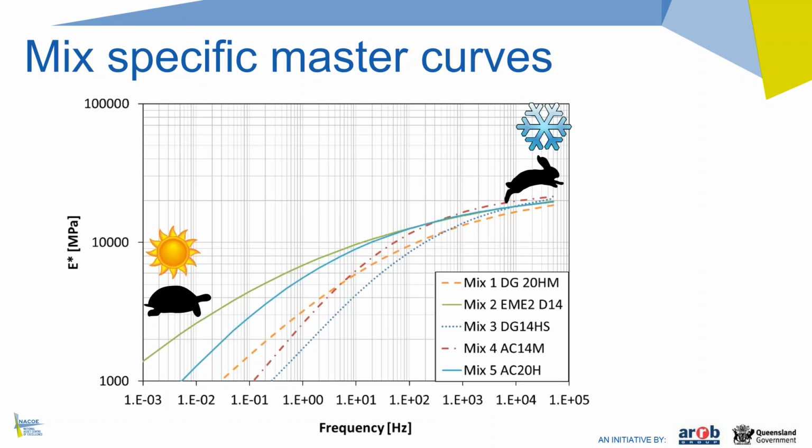No, well, the answer is actually that it does asymptote on both sides. The sigmoidal model is actually a symmetric model. That means the asymptote that's on one side is also on the other side. The thing the slide doesn't show is the current Austroads method, and also the current design, the current TMR supplement, limits the master curve at 1000 MPa. So that is what I did here as well.